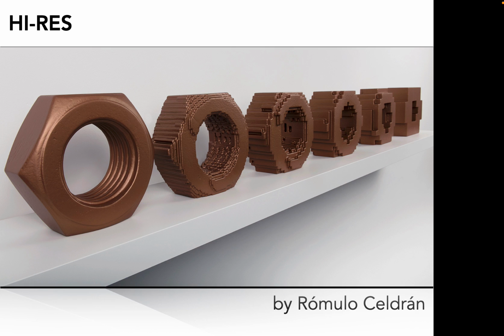So we're going to try to analyze an object, a very complex object. And then what we try to obtain is an approximate solution to a boundary value problem. And of course, what we do is we try different levels of refinement because we would expect that as we refine the finite element mesh, that is, as the finite elements get increasingly smaller, our solution would be better. That's intuitive, right?